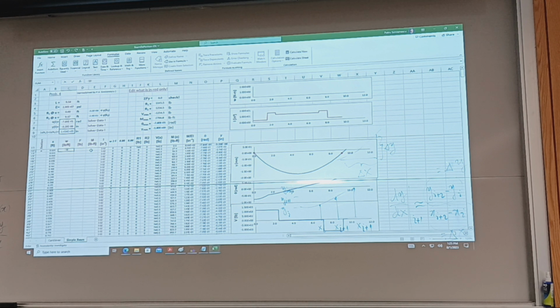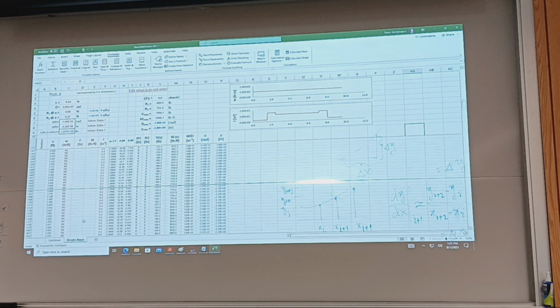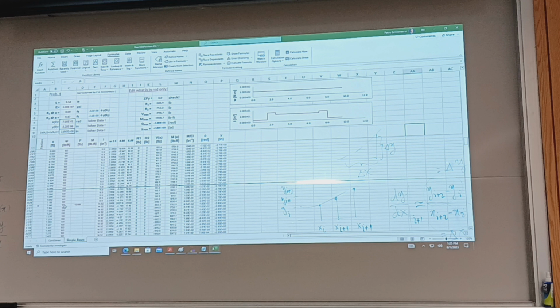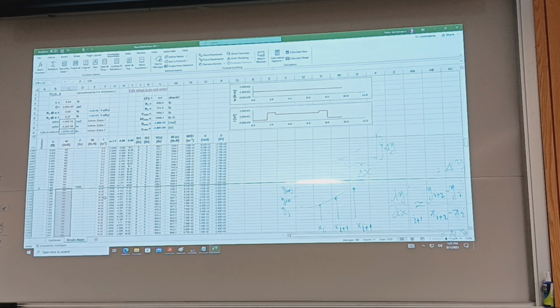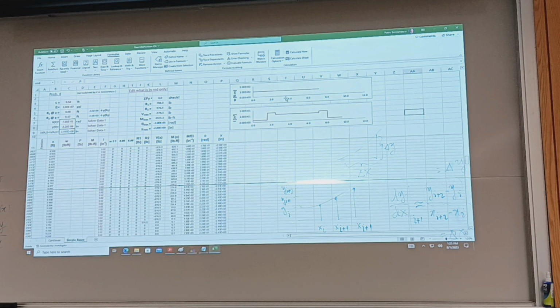So 10, negative, we went to negative. I said negative 10. And then keep this all the way to the bottom. And you can see it here, the graph populated. If I want just half of it, say beginning with point B, to no longer have a distributed load, I just delete it. And it updated the distributed load graph.